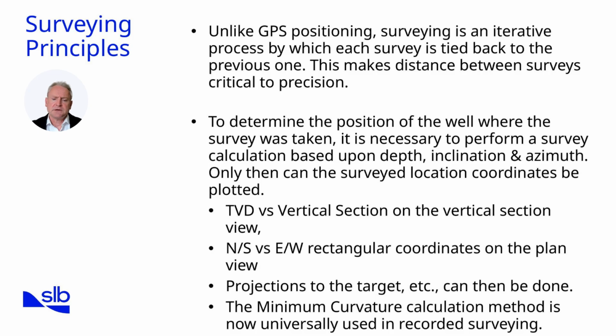The key principle is precision. Because surveys build on each other, the spacing between survey points must be managed carefully. Too far apart, and your accuracy drops. Too close together, and you lose efficiency. Understanding how survey data is collected and processed ensures that well trajectories match geological targets and avoid collisions with other wells. Surveying is the link between planned well designs and their execution in the subsurface.